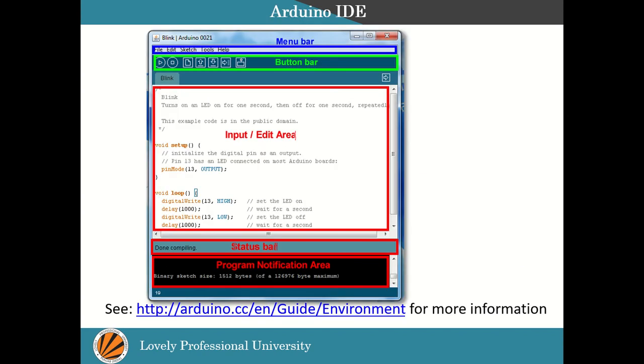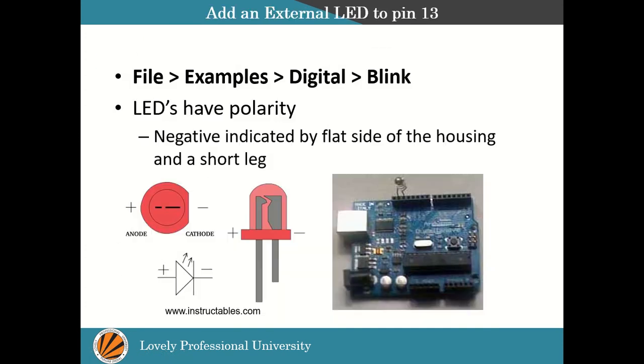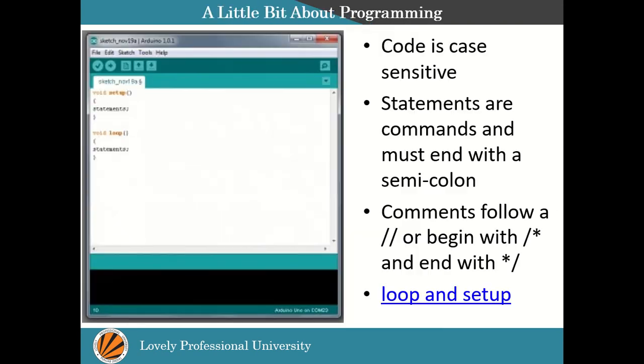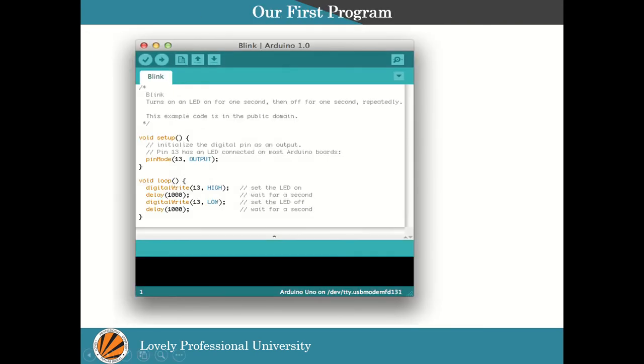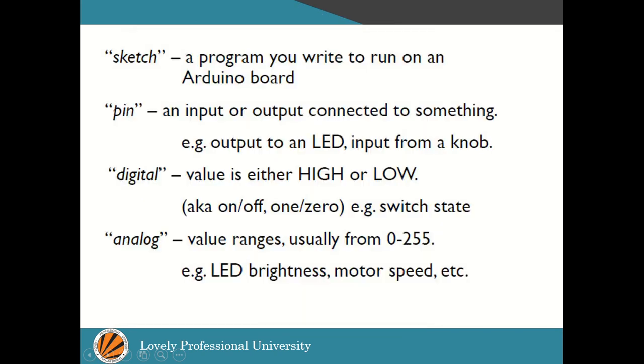Now, looking at the previous slide, it will be a void setup and an empty function, nothing has been written in it. So let's start with the blinking of an LED. For blinking an LED, first of all you should know how to write the pins and how to configure the pins. So to configure the pins, let's start with the basic programming. First of all, you need to set the pin mode. In this setup function, you need to select which particular pin you are going to work with and whether you are making that pin an input pin or an output pin.